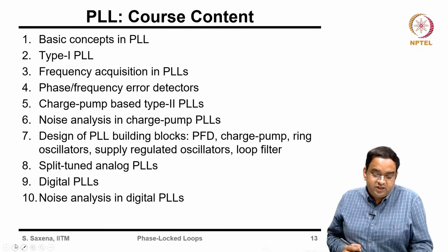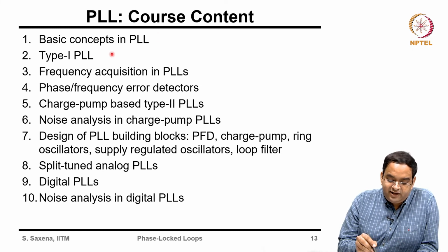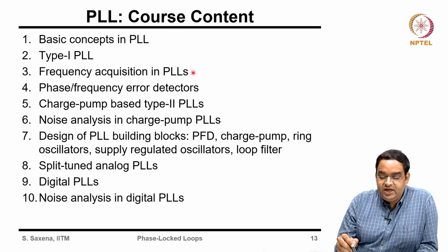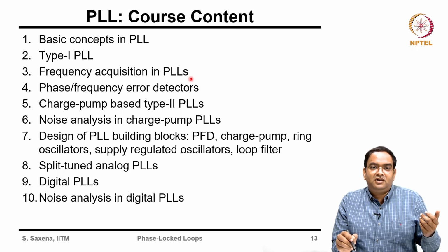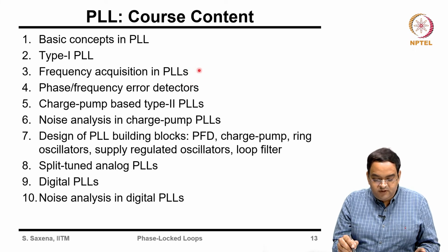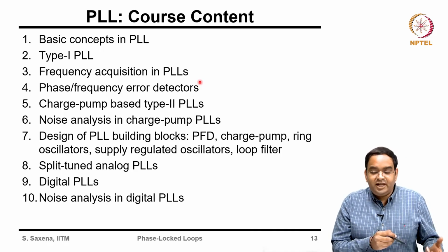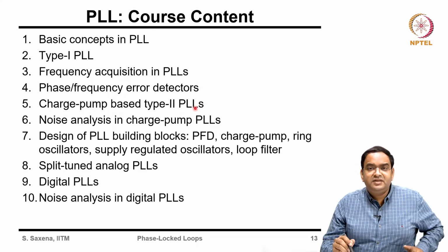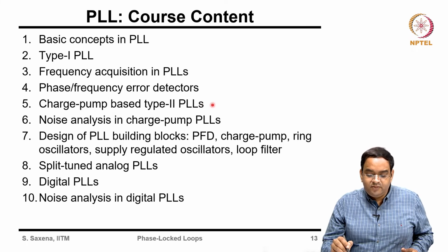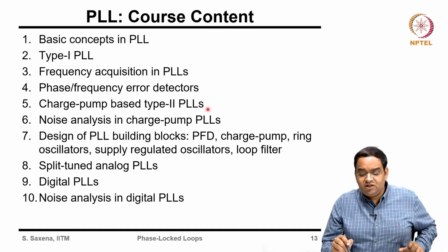As the course content, we will go through the basic concepts in PLL, then a very standard type 1 PLL. Later we see how we acquire frequencies in PLLs. You start your PLL, it will not acquire the frequency as you desire immediately, it will take some time. Then we will start designing the PLLs, understand how to reduce the error, which block helps in reducing the error and how to actually measure the error. Then there will be charge pump based type 2 PLLs. You can say this is the main workforce for all kinds of PLLs. You can implement it differently, but the basic logic lies here.